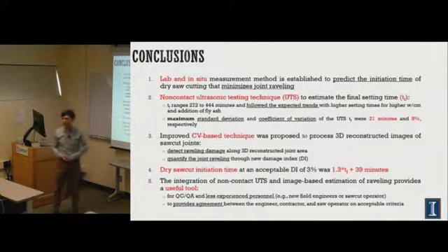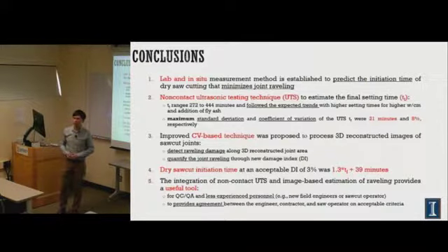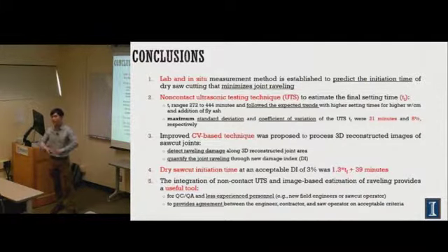Yes. For implementation, and maybe you're going to get to this, in the field, would they use similar ultrasonic equipment for determining the setting time? They never use it, but I use it. But I'm saying, this 1.3 times the time of final set plus 39 minutes, to pinpoint that time, they have to know the time of final set. Yes. Are you proposing that they use an ultrasonic method, or the previously determined set time for that mix? Because that could vary due to environmental conditions, so humidity and temperature, say. Exactly.